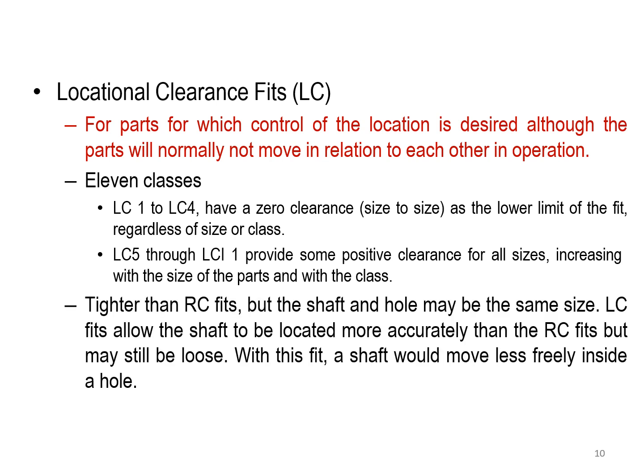It is tighter than the RC fit, but the shaft and the hole may be the same size. The locational clearance fits allow the shaft to be located more accurately than the RC fits, but may still be loose. With this fit, a shaft will move less freely inside the hole.